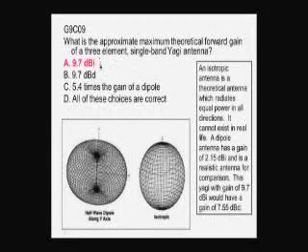But most antenna manufacturers do use dBi in rating their antennas. So you need to watch for that. And if they just say dB, then you can be pretty sure it's dBi. If they're rating it as dBd, they'll tell you, because the number will not be as high.